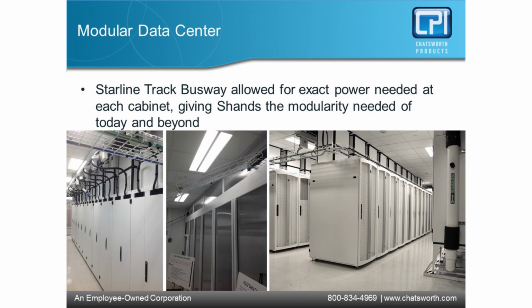The nice thing about our plug-in units, they're grounded before the phase bars are even engaged from the plug-in unit perspective. So anybody who's doing work can be guaranteed that the plug-in units are grounded before any phase connections would be made. Then there's the NFPA portion of this, which is the live work component.